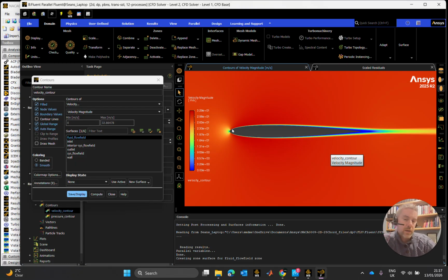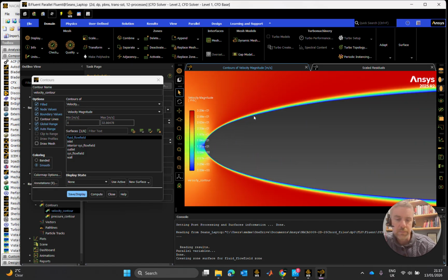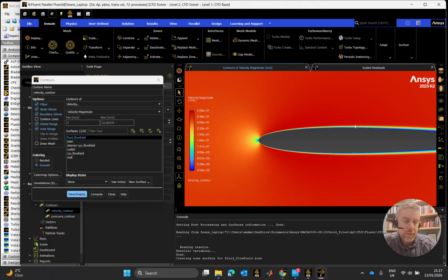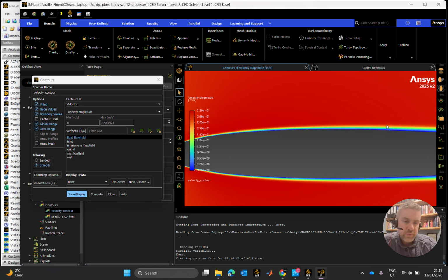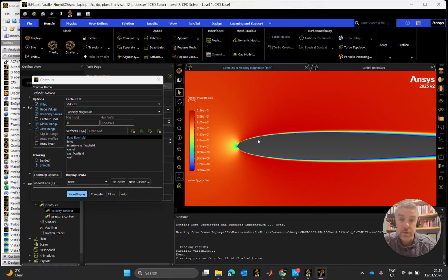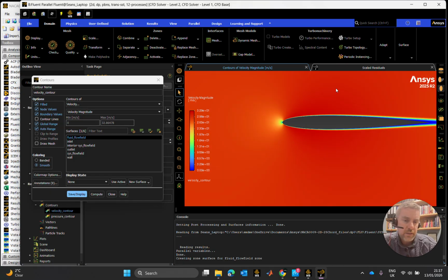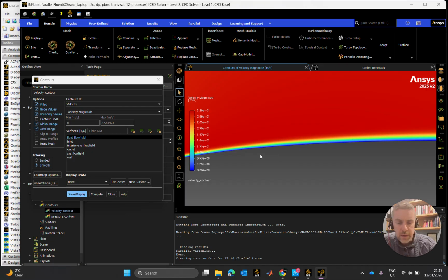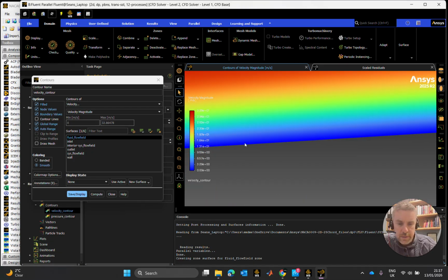What I would say as well, especially when we're looking here at the velocity, something that's always worth noting and making sure that you're fully aware of, and if it makes sense, let the judges know you're aware of it, is the boundary layer. The boundary layer in itself is the area of the flow close to the surface in which viscous effects have an influence in part. So we can broadly ignore the influence of viscosity out here, or any sort of shears out there, but definitely within this region we can't.